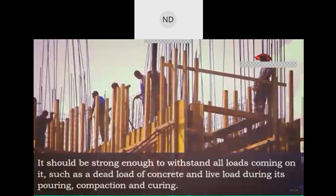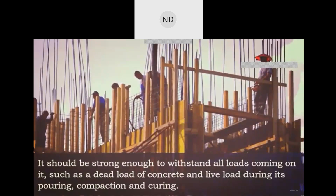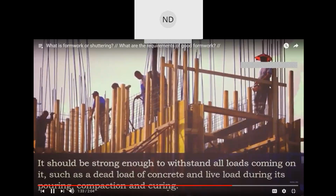It should be strong enough so that deflection is minimum or low. It should be as light as possible. The surface of the formwork should be smooth, and it should provide easy stripping. All joints of the formwork should be strong.